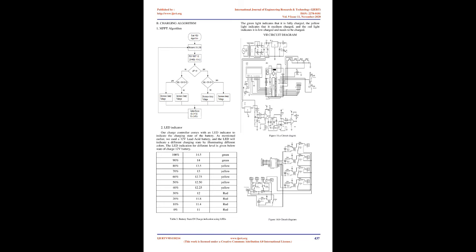1. Trickle charge, 1st stage, from T0 to T1. This first stage is active when the battery voltage is below the value VTC. This voltage value, specified by the manufacturers, shows that the battery arrives at its critical discharge capacity. In this condition, the battery should receive a small charge current defined by ITC that has a typical value of C/100, where C is the normal battery capacity with a 10 hours charging process.